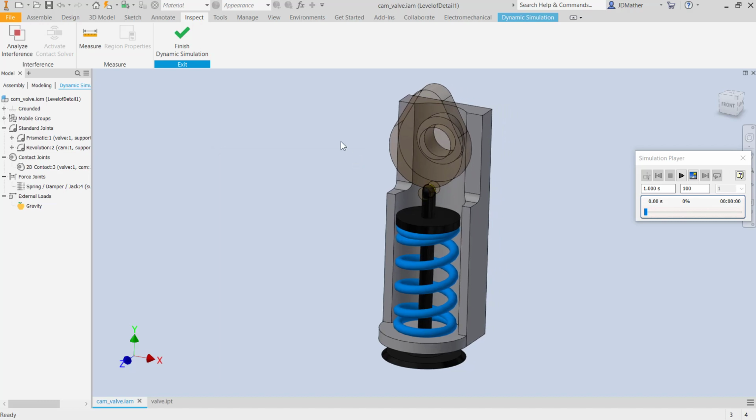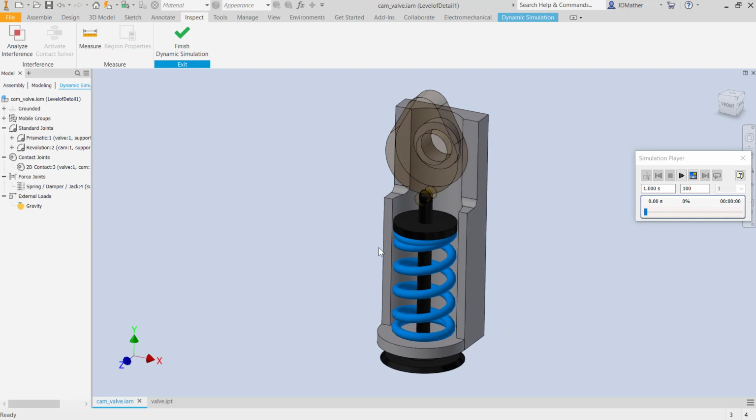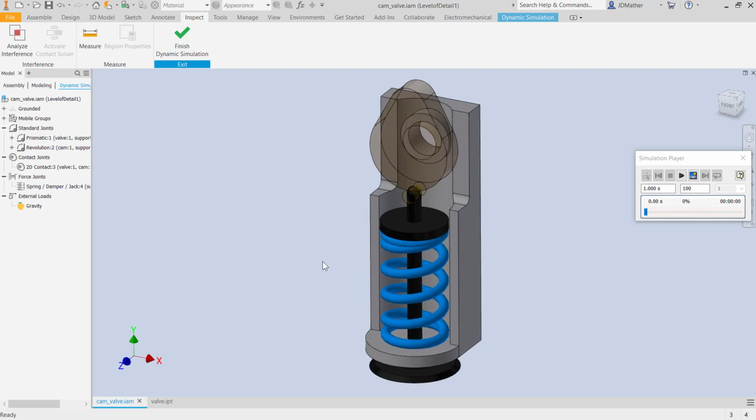So as you go faster and faster, when you approach 7,000 RPMs, the valve wants to float instead of returning back up against or keeping against the cam. It'll try to float in space, open when it's open. And if the piston comes up and that valve is floating, it will hit the top of the piston and either bend the valve or put a hole in the top of the piston. In any case, your engine is going to stop working. So it takes two incredibly strong springs in order to keep that valve against that cam face when you get over a certain number of RPMs.